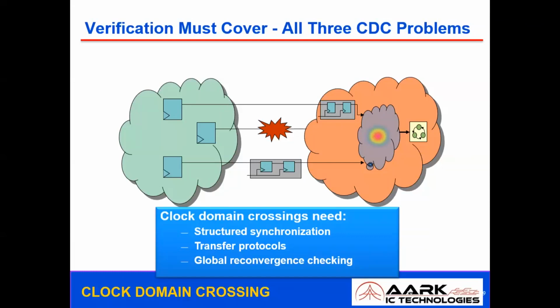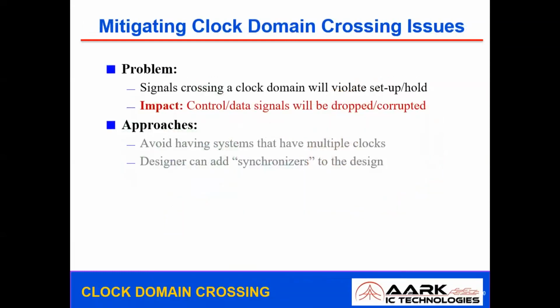If it is a broadcast, you can broadcast it, and whoever wants to take it can take it. So the protocol is not required when you go for broadcasting. But when you are transferring data between two peers, you should definitely have a proper protocol between the two peers so that you can avoid the loss of data. The same technique we should also adopt in addressing CDC issues.